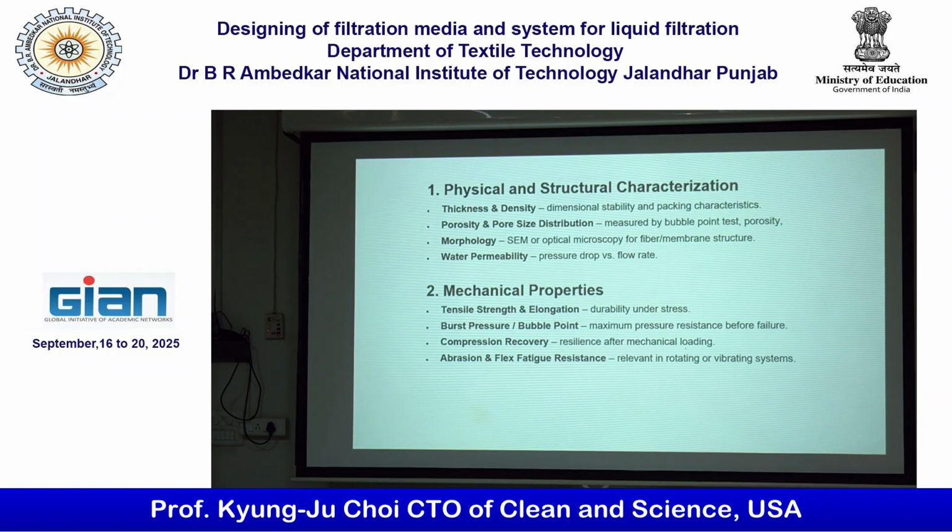Here, the media characteristics. First, physical, structural characteristics. This is what we normally do. Once we receive the filter media, then normally we measure thickness. Sometimes we measure the density, not always. For liquid filtration, certainly porosity and pore size distribution is really important. So for liquid filtration media, we normally measure the thickness.